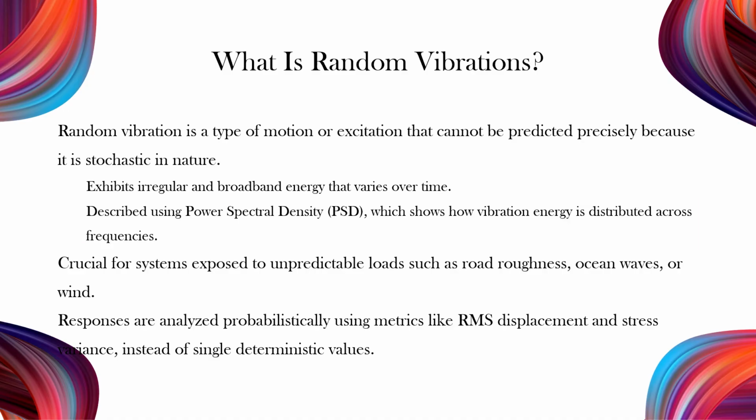In practice, random vibration analysis is vital when structures or systems face unpredictable loads, such as road roughness, ocean waves, or wind. Since these excitations are uncertain, engineers analyze the response probabilistically, using measures like RMS displacement and stress variance instead of single deterministic values.